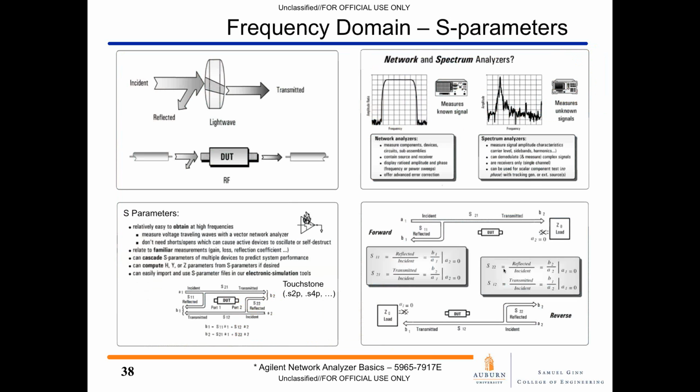So if we dig a little bit down into the frequency domain, a little bit of the educational aspect of this, we typically are interested in bringing out the S parameters. If we look at a system that would consist of our DUT, the device under test, there's an analogy with light in terms of power moving towards, through, and reflected from this device. So we can use S parameters to characterize the amount of power that is reflected and the amount of power that's transmitted through the system, so we can determine how well that system is performing and how it interacts with the rest of the system.